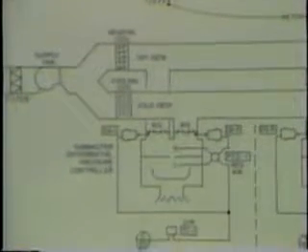System type number 3. Dual duct variable air volume systems have hot and cold air available to the terminal units at all times. When the space temperature is at the low end of the thermostat's throttling range, the terminal unit's hot duct volume damper is open and the cold duct volume damper is closed.